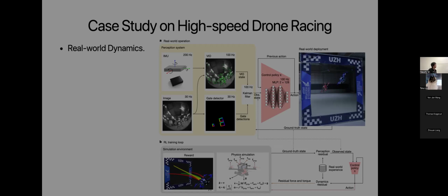But what you could do is learn these models from sim-to-real, so that in the next round of training, when you're training in simulators, you apply the physics in the simulator and add the residual physics you learned from the real world. In this case, your model is essentially learning on dynamics that are closer to real-world dynamics. Although that's still not going to be perfectly aligned, this will improve the performance by a large margin.